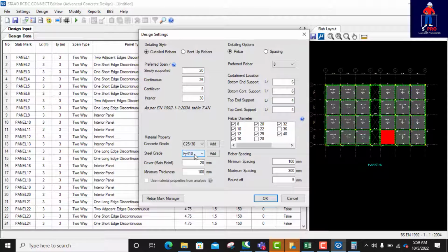So Eurocode actually specifies 500 for steel grade. But fabrication and production of steel members can, due to human factors and some other things, reduce the strength. If you use 500 to do your design, it will be giving you something very strong and sweet. But in case the strength is not 500, you might be designing something that will collapse the next day. So it's better to be on the safer side. The cover here, I will use 50.